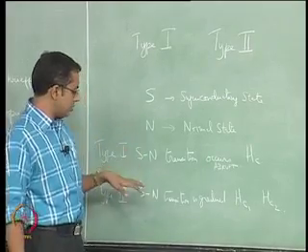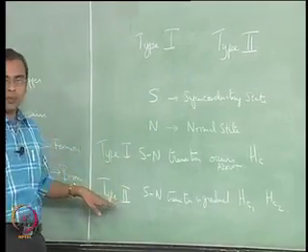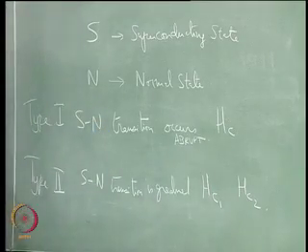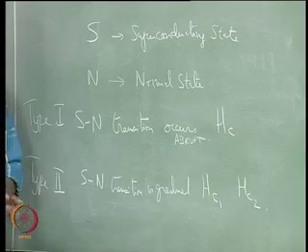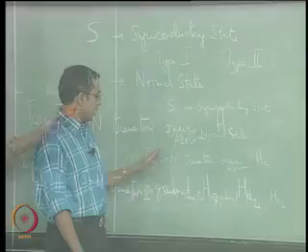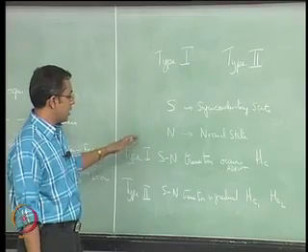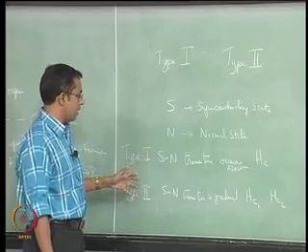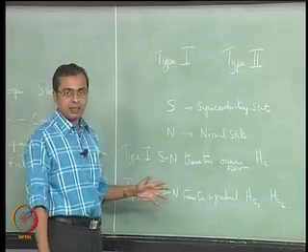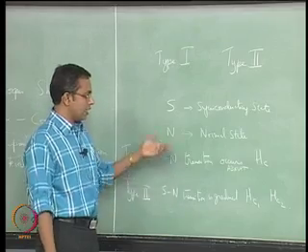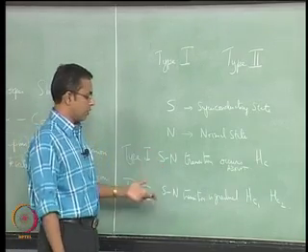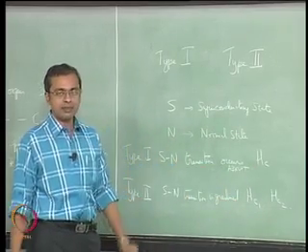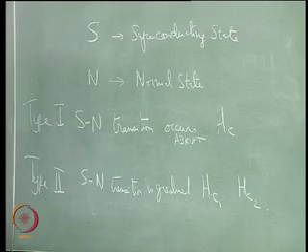The advantage though is that in some usages the type 2 superconductor becomes preferable because you can handle much higher fields. That is the reason why sometimes type 2 superconductors may become preferred. So even within the superconductors you have this variation in the type of superconductivity that may be present within the material, and therefore you have different classes of material, which are either type 1 or type 2. If it is a type 1 you will only have an HC, whereas if it is a type 2 you will have an HC1 and an HC2. So that is the difference between them.